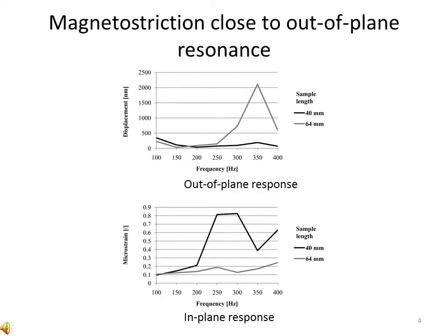While the experimental setup demonstrated non-resonant behavior in the range of its intended use, an alteration was made in order to display the effect of the out-of-plane resonance. The length of the test sample was increased, therefore lowering the first out-of-plane natural frequency to 314 Hz.